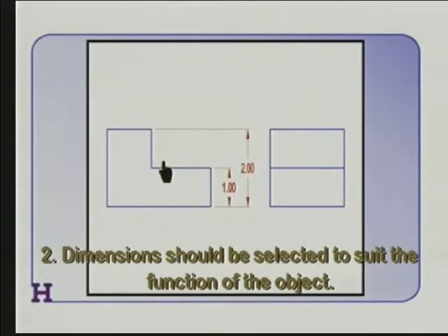If we don't know, we have to make a guess, and unless you know the function, nobody can say your guess is wrong. The rule of thumb is dimension stuff instead of space. Remember, we don't want to put both of those in there. So in this case, we'll dimension the height of this feature rather than the depth of that step. There may be a part where the depth is more important, and remember, this tolerance buildup will cause us problems if we don't dimension it properly. Next principle.